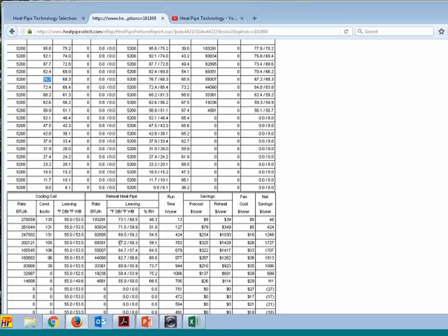So I've essentially oversized my wraparound heat pipe to hit my design or my terminal reheat condition more at my part load conditions rather than just focusing at my design conditions. So that's one example that you could run through by just seeing what happens with a 2-row, and then going up to a couple rows higher but making it controllable, especially if you're looking for year-round recovery at your part load conditions.